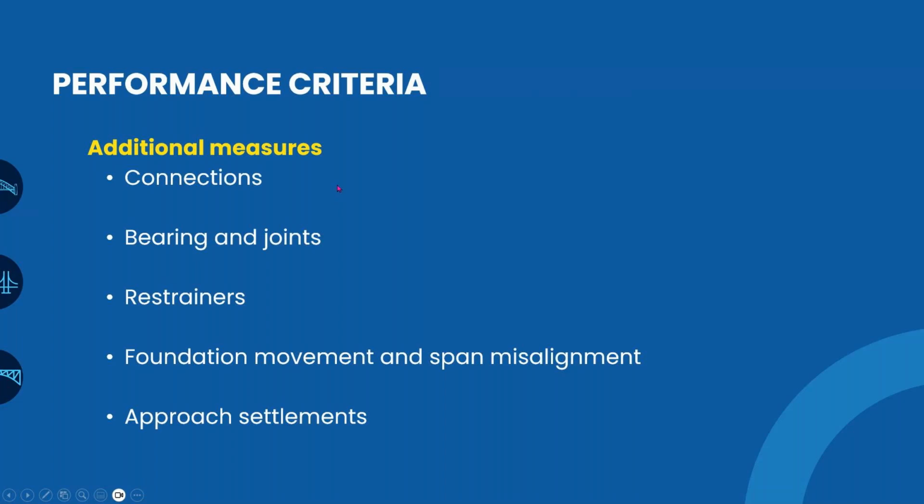Similarly, we also need to check additional measures, such as whether the connections, the bearings, the restrainers, etc., are within the limits of their deformations. We also need to check the foundation moment, and whether the approach settlement is restricted or not.